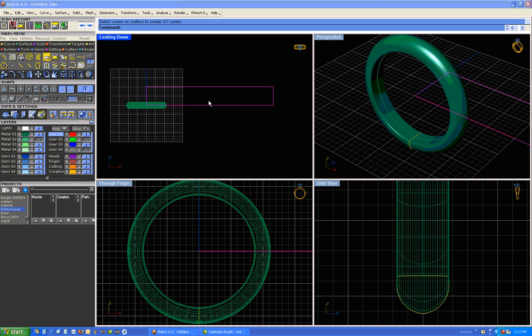Sidebar. Depending on the profile shape used to sweep your ring, Create UV Curves may extract the entire surface of the ring or extract from the center line to any sharp, like a 90-degree angle, edge of the surface. Each profile acts differently, so you should be prepared for both.